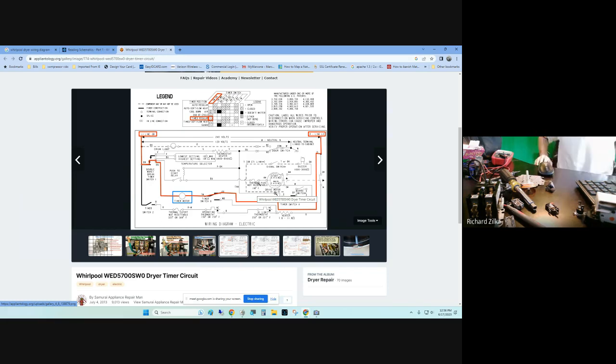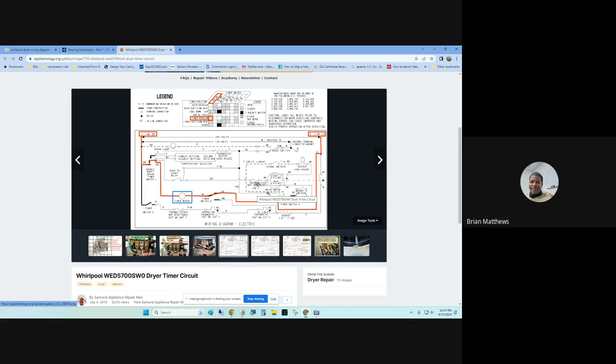Okay, so that comes to something I lecture a lot. You go to someone's house and their dryer's not working. Hey, Joyce, I need you to check out my dryer. It's not running. Oh, well, sir, the reason it's not running is your thermal fuse is open. I got a new one in the truck. I can put a new thermal fuse and the motor's going to run again. But did you fix the problem? No. Well, that's temporary.